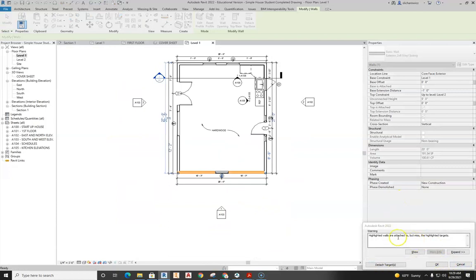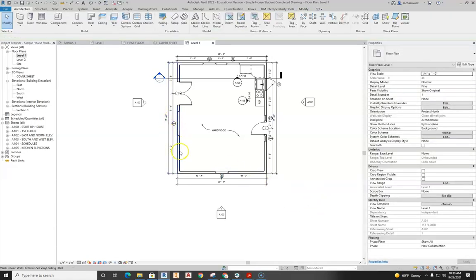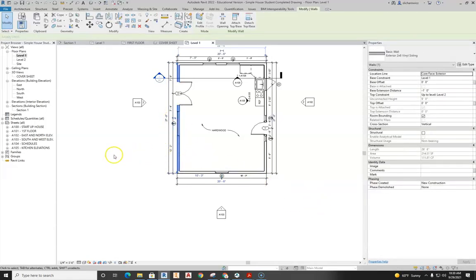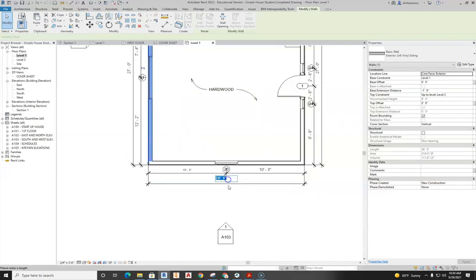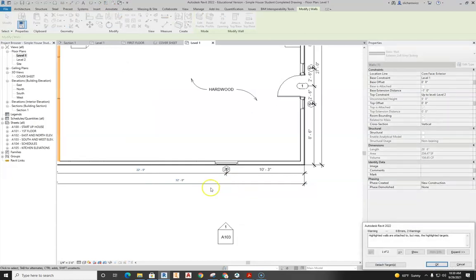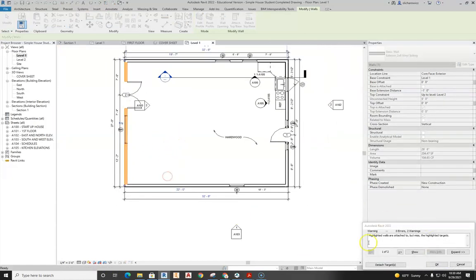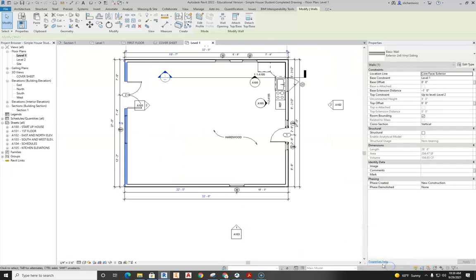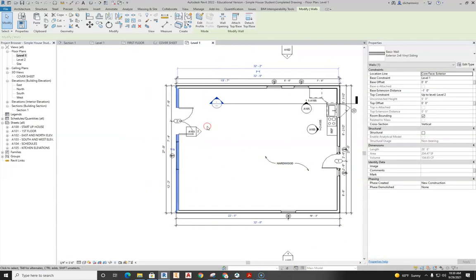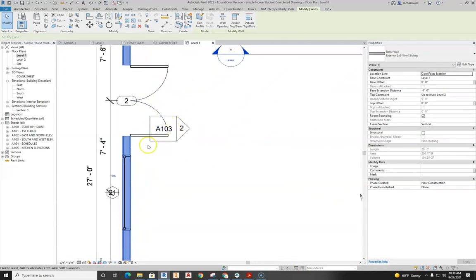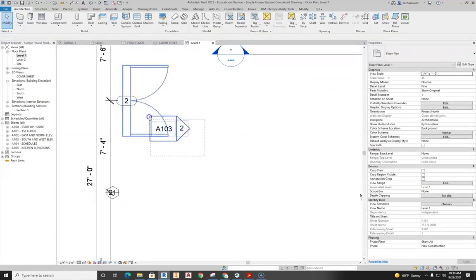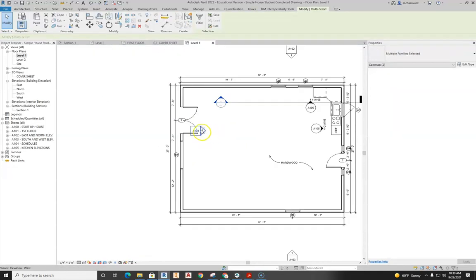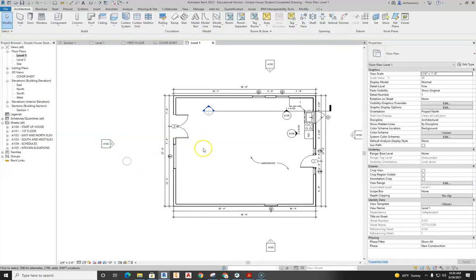Done. Here it says highlighted walls attached to but missed the highlighted targets. That's fine. That's probably something to do with the floor. Not a problem. Now I want to push this wall out. This should become that 32 feet, 32 8 inches, and that pushes that wall over. Okay, again, detach the target. That's fine because we're messing and changing everything. So with this setup, all right, I can see here I got this little elevation thing kind of hiding out here. I don't want that in my drawing, so I'll highlight it, stick it over here, move that out.